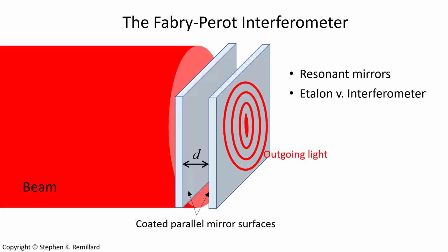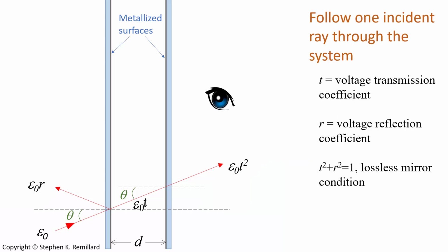But when you have two reflecting surfaces just facing each other, you can get resonances that you can't control by moving the mirrors, and it's often an unwelcome property of a system, and it's often referred to as Fabry-Perot modes. You'll hear this term both in optics and in microwaves to refer to resonances that occur when you have two counterfacing reflecting surfaces.